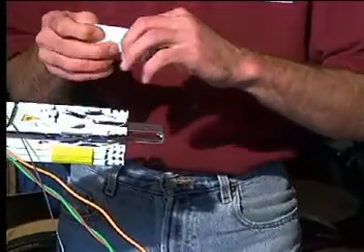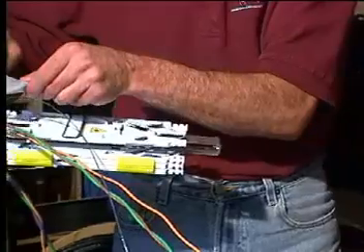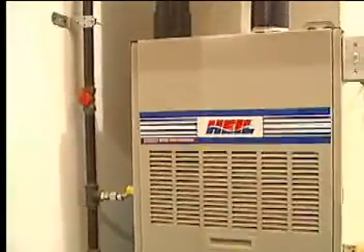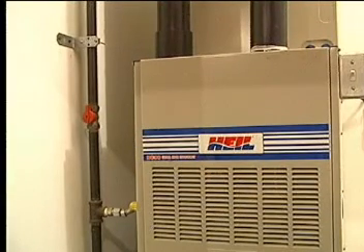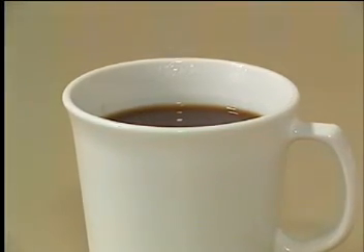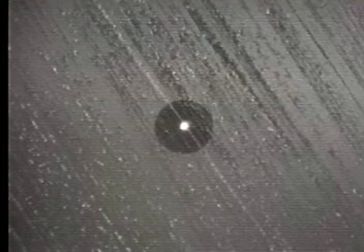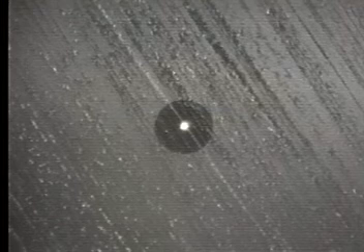Along with water vapor come tiny particles of dirt, smoke, and pollen, along with droplets of oil from both mechanical sources, like fans and heating systems, as well as biological sources, like human breath, and even nearby food. When the pad is used to wipe a connector end face, contamination can be smeared across the surface, resulting in a type of signal loss called haloing.